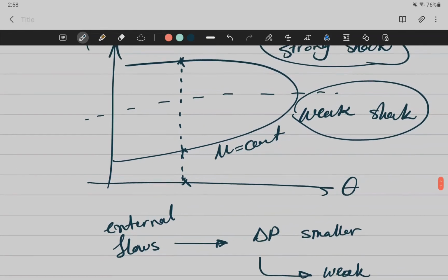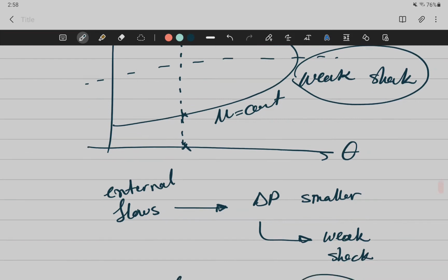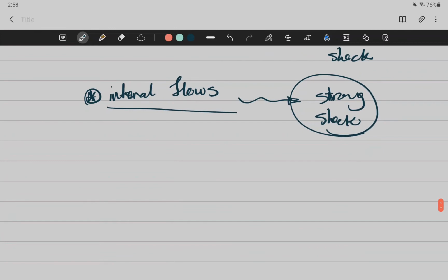Why is a strong shock closer to normal to the flow than the weak shock? What is the strongest shock wave that we discussed? Normal shock. So a strong shock is going to be closer to normal shock, right? And because we have a concept called weak shock wave, this essentially means that after an oblique shock, we can still have a supersonic flow.